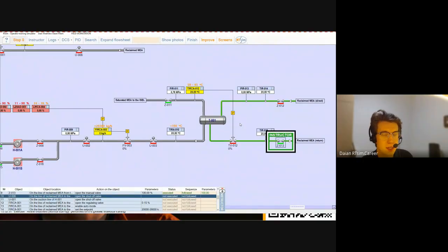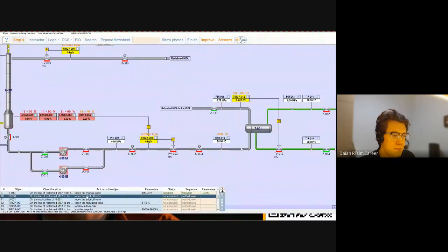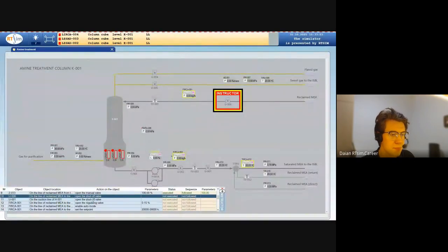if we start heat exchanging, start from the cooling medium. If we shut down our heat exchanging system, we should first of all stop the heating medium. And the others, then the next step.